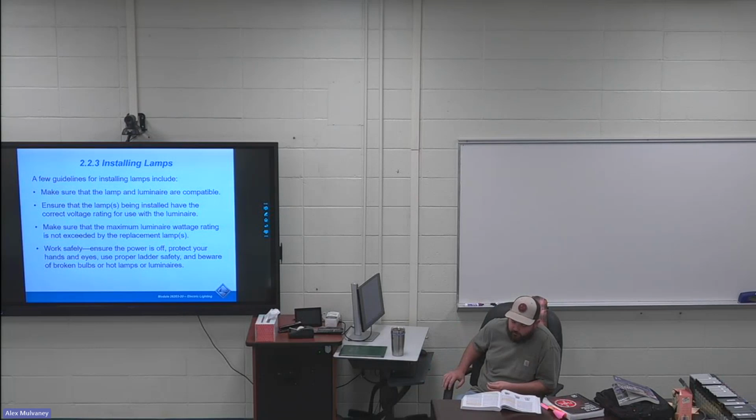224 on page 19, fluorescent luminaire ballast. First sentence is highlighted on there. In fluorescent luminaires, the ballast performs the following functions. Second bullet point highlighted. It regulates electronic current flowing through the lamp to stabilize the light's output. Usually you have a high inrush current and then it steadies out pretty quickly. It's got to have that high voltage to get the particles inside moving, and then it balances out and gets you a stable light after that.